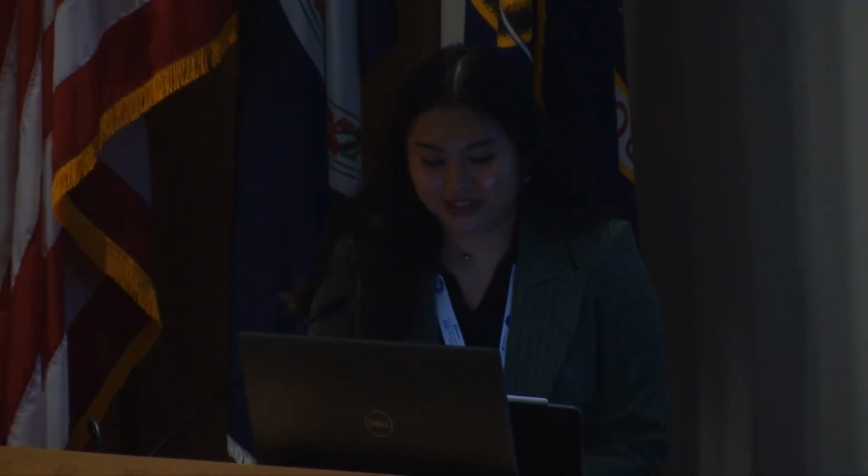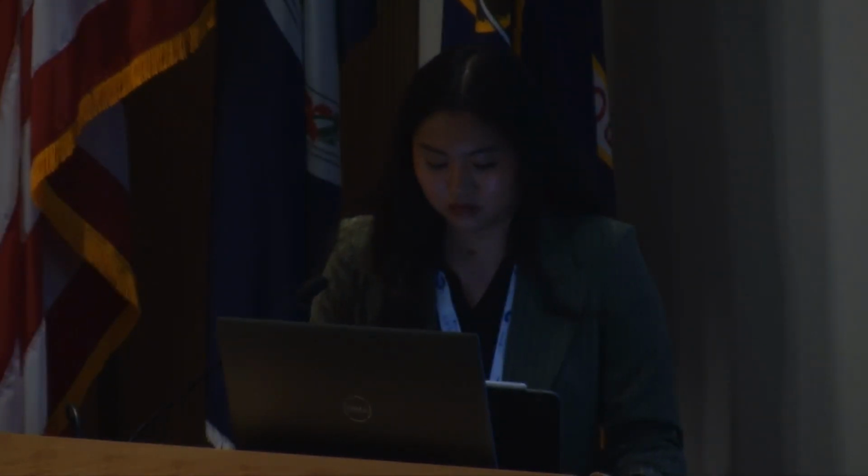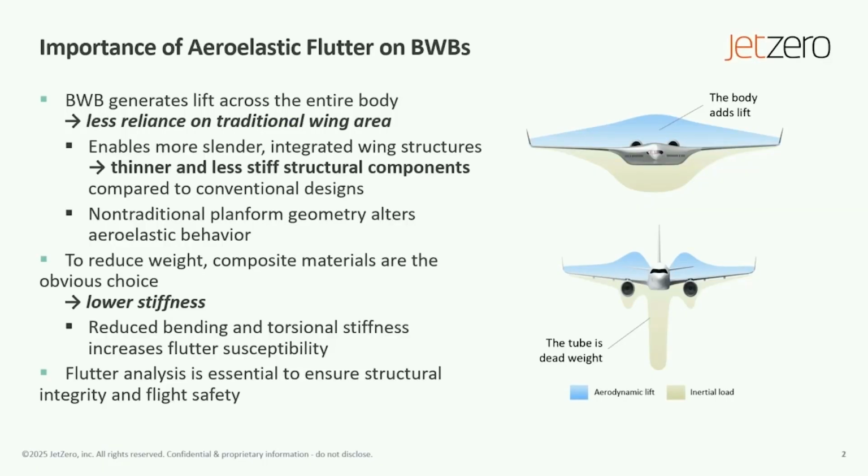In this presentation, I want to give you a little summary before I start. I'm going to be talking about why flutter is so important for our JetZero aircraft and how HyperX fits into our sizing workflow, the results that come out of the workflow, and also the future development that we're hoping to continue working on to better the workflow and obtain better results. I'll be talking about how we use HyperX and Nastran Sol 200 to do aeroelastic flutter sizing on the JetZero blended wing body.